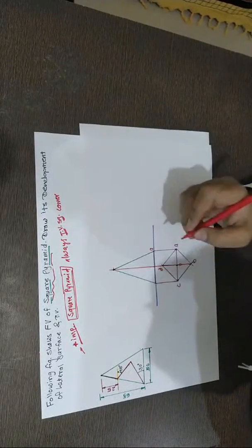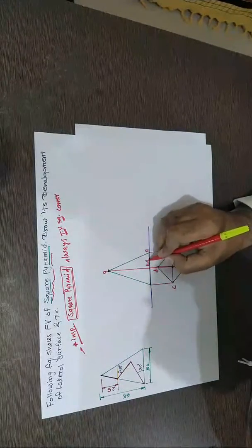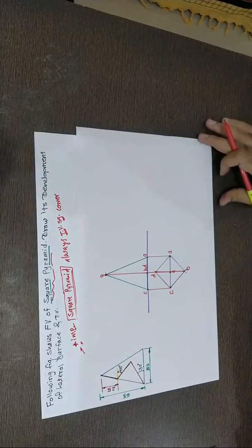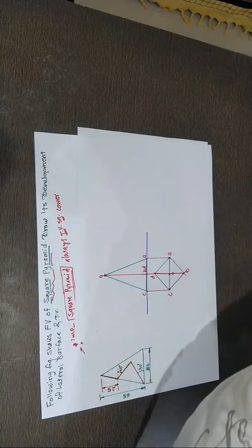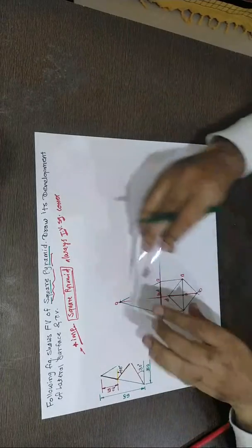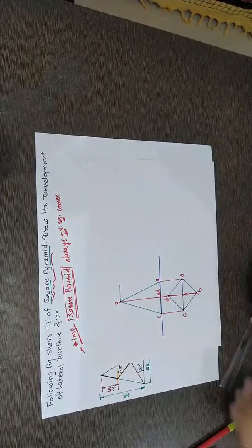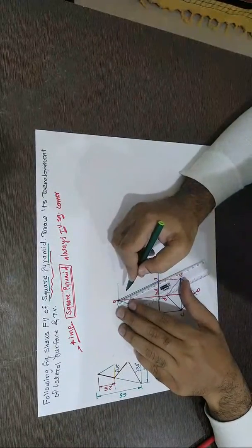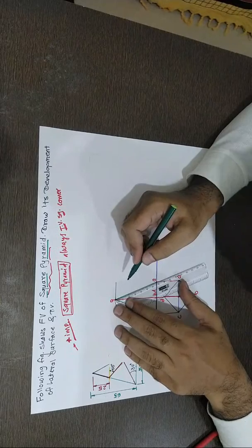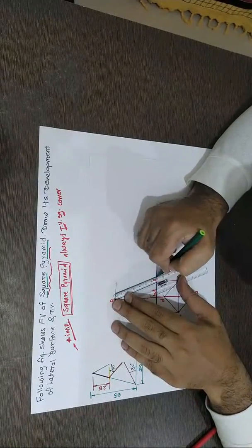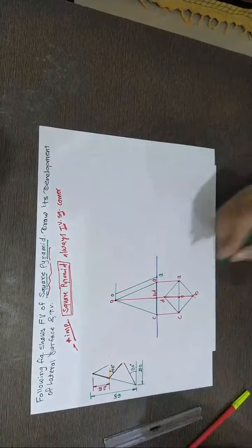Now give the notation. Oh, this is A, this is B comma D, and this is C. That's the square. Now yes, you can take OA as a radius, same way, similar to the last question. Means pyramid, of course. And draw one reference line, and parallel to OA edge, you draw one more edge, or you can continue, no issues. But we need to draw a very clean and neat drawing, so we are mostly following parallel to this. I am drawing one more edge. So this OA and this is same OA I am drawing for reference, which is parallel to this.